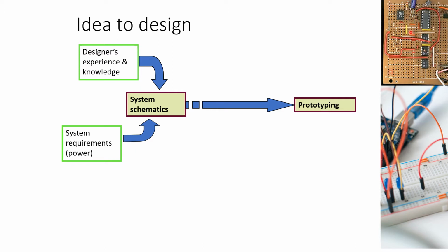So once you have the schematic diagram, one option is you can do the prototyping, either using this kind of prototyping board with solder, or you can use a solderless board like a breadboard. You do the prototype with different wires and see whether you are getting the desired output. However, this option is kind of outdated, I would say. When you go from schematic diagram to prototype, of course, you need to have physical components and then you connect them.